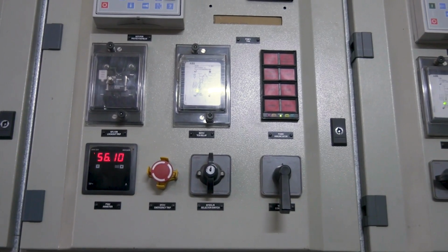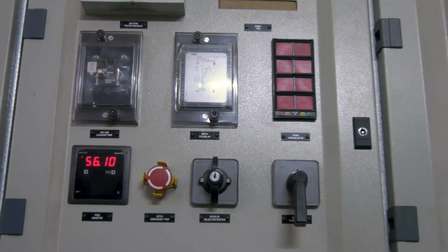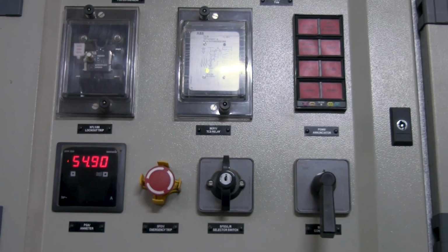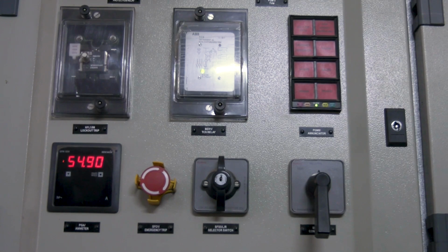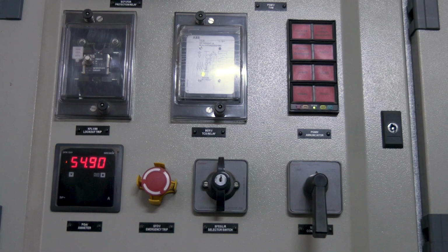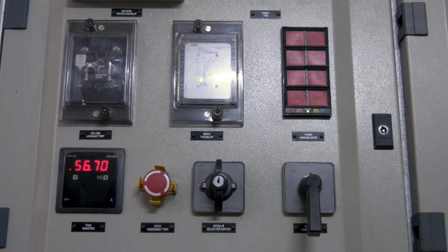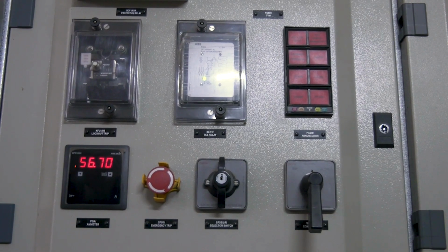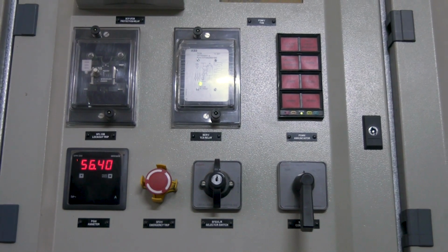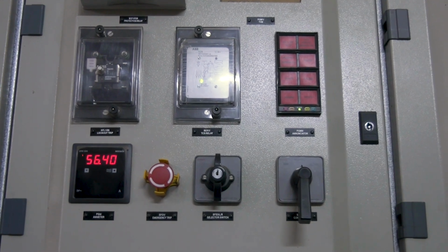Moving on, we have the lockout trip relay, which prevents re-energizing the system after a fault until manually reset. The TCS relay monitors the integrity of the trip circuit, the PGIM annunciator provides visual and audible alarms for various fault conditions, a digital ammeter displays current in the feeder, an emergency trip button allows manual system tripping in emergencies, and various selector and control switches handle local and remote operations and manual circuit breaker tripping or closing.